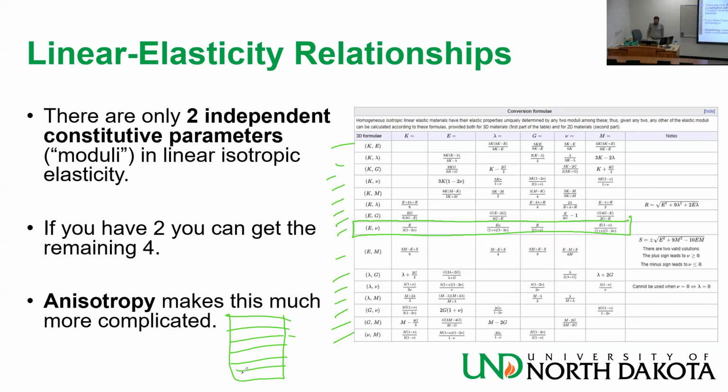And yeah, this kind of notation that we learned today, the Voigt notation, it helps a lot in this kind of models. And this transverse isotropic model is the next level after isotropy. So I want to depart from isotropy, which is a very simple model, same values everywhere, and I want to have transverse isotropy.